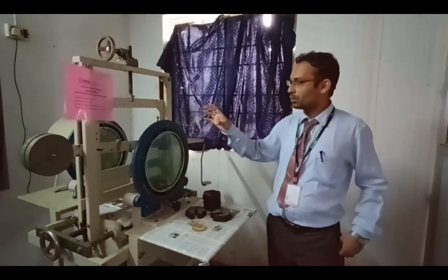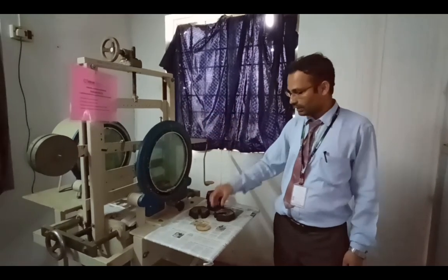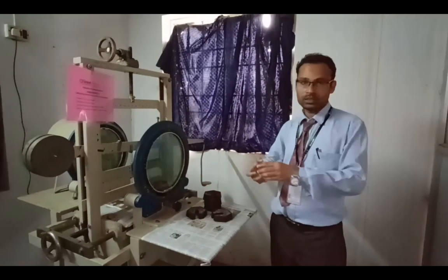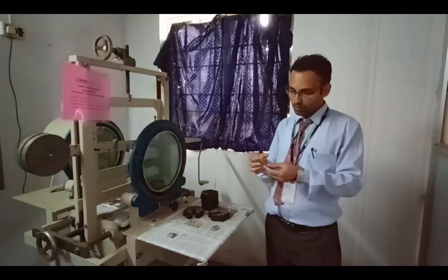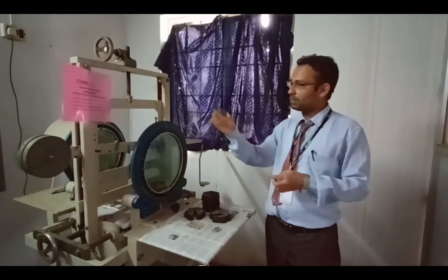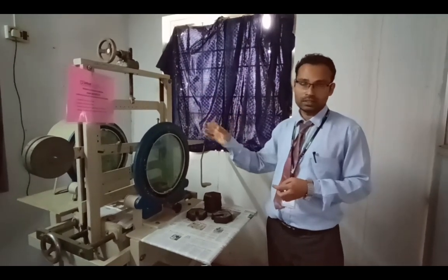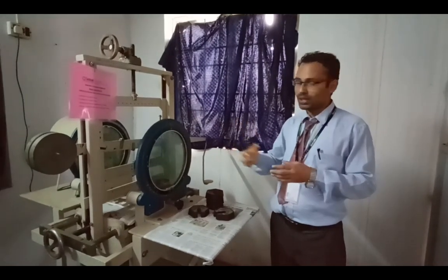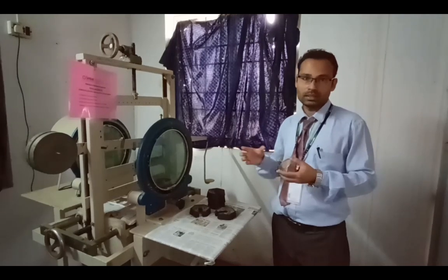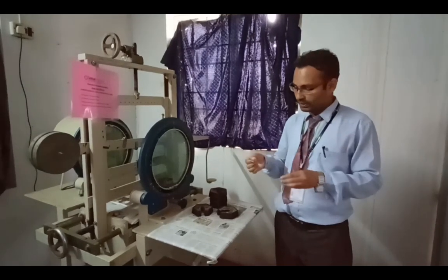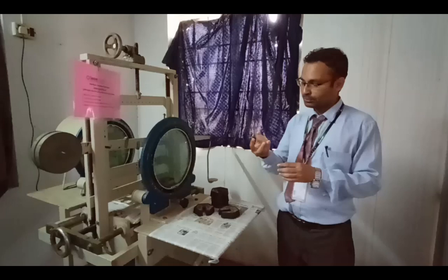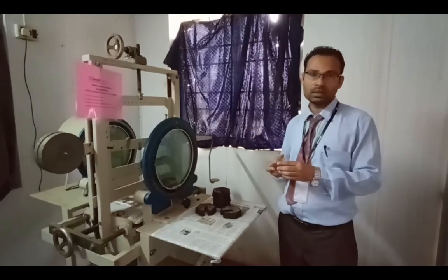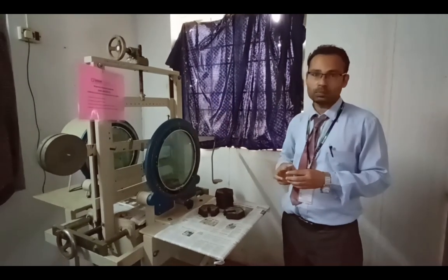So here what we are going to find: you take a circular photoelastic specimen component, and find how many fringes occur in this element with the help of this circular polariscope setup. Finally we are going to find the principal stress of this photoelastic material. So the aim of the experiment is to calibrate the given photoelastic specimen and find the difference of principal stresses using this circular polariscope setup.